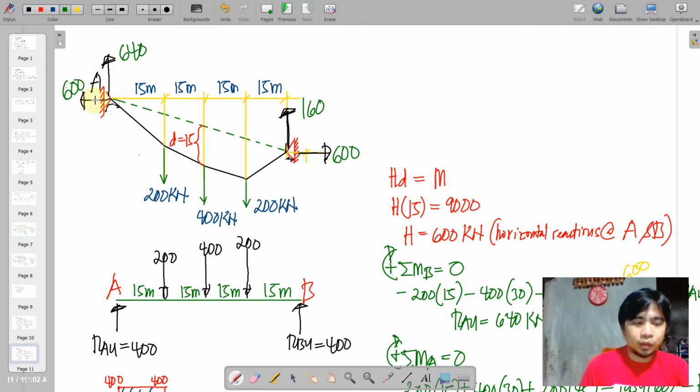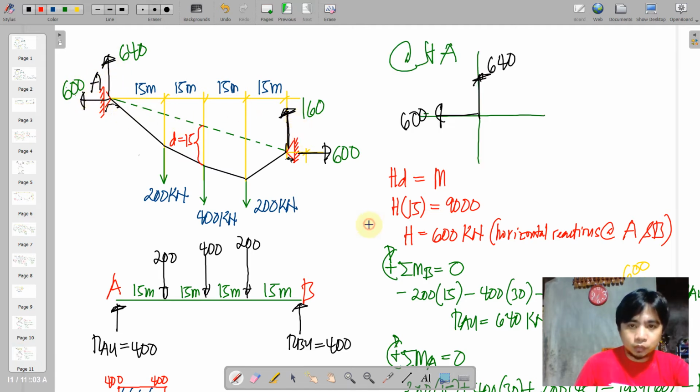Okay, so we will get its joint. So at joint A, what is in joint A is the two reactions, vertical and horizontal, and remember that this shall yield RA as its resultant, which is actually collinear to your cable here. So if I'm going to label this as 1, this is T1.